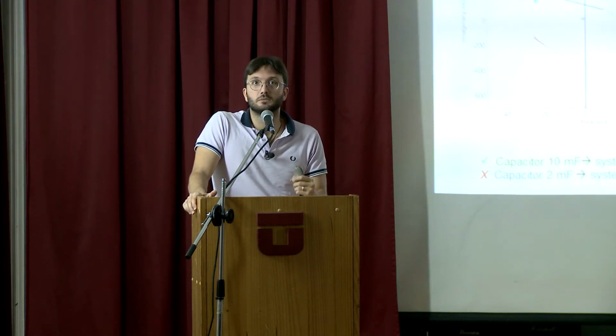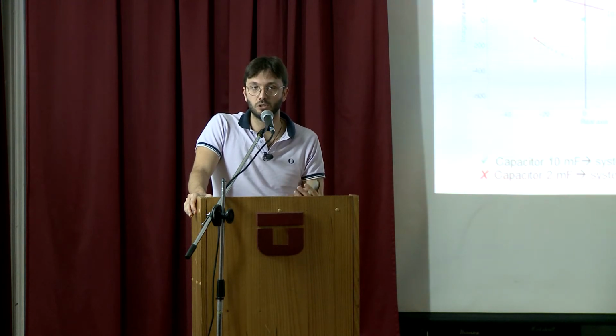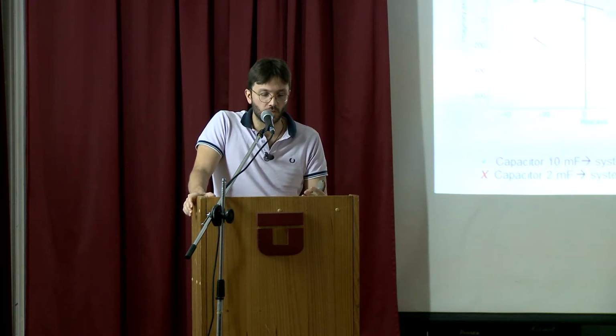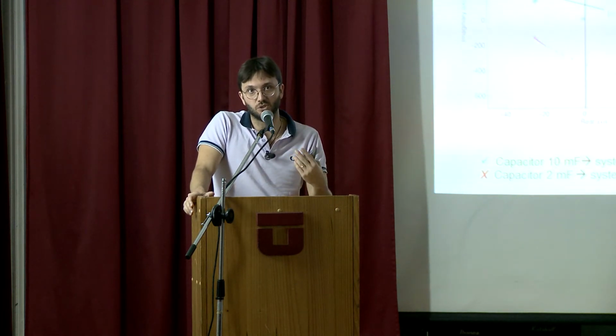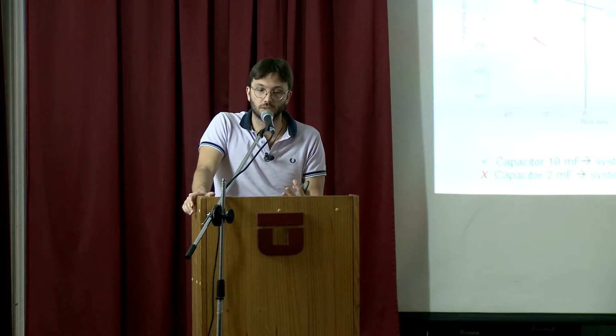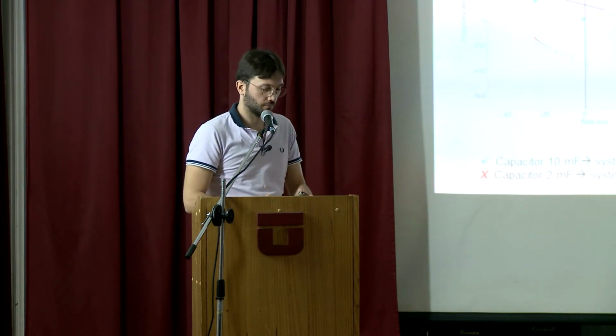So it is tricky, because interfacing with power electronics converters whose parameters you don't know, you really have to see how sensitive the system is. You have to do some sensitivity analysis. You have to take into account that you don't have the control of what the manufacturers do.